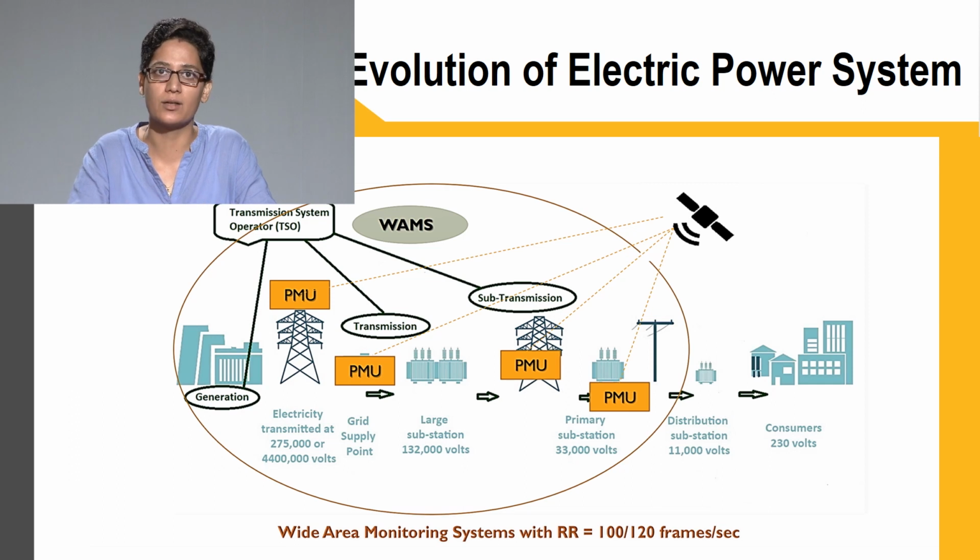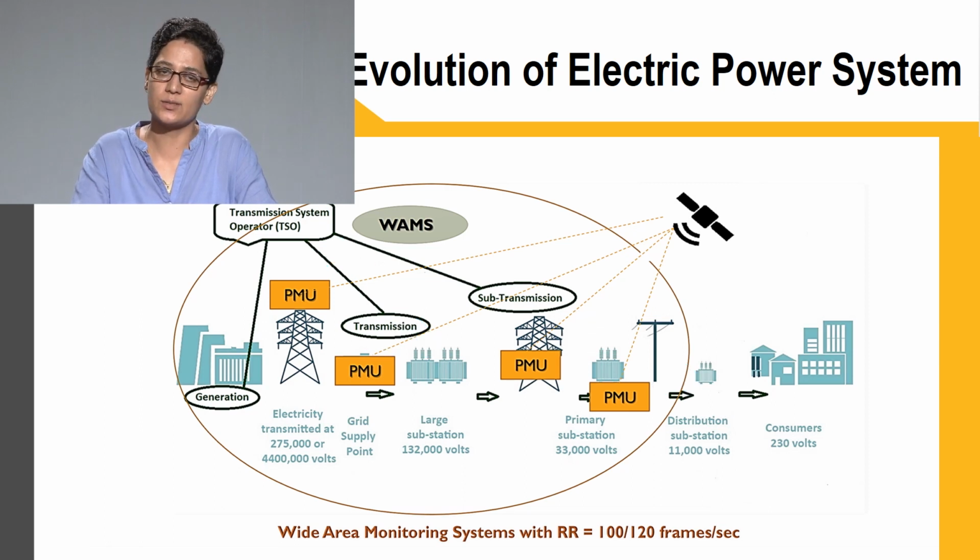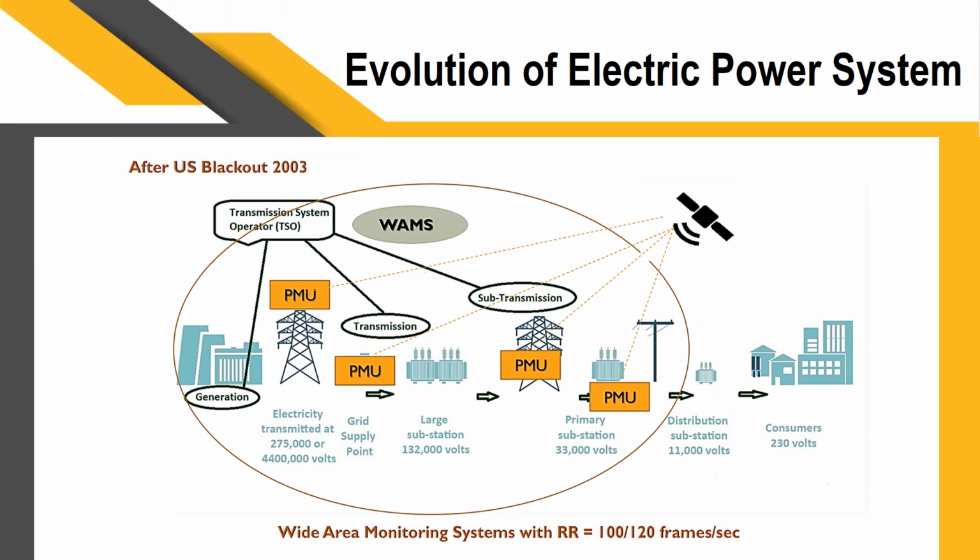Under one of the major Power Grid projects, India is undertaking to deploy a massive number of these sensors, these measuring devices known as PMUs, somewhere around 1400 across the Indian grid. Once all these PMUs are in place, along with the required communication setup, these real-time and synchronized measurements will be sent to a control center where the system operator can take an informed decision and see the real-time monitoring picture of the power system.